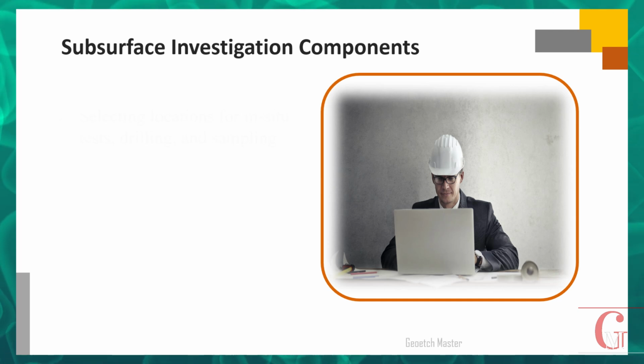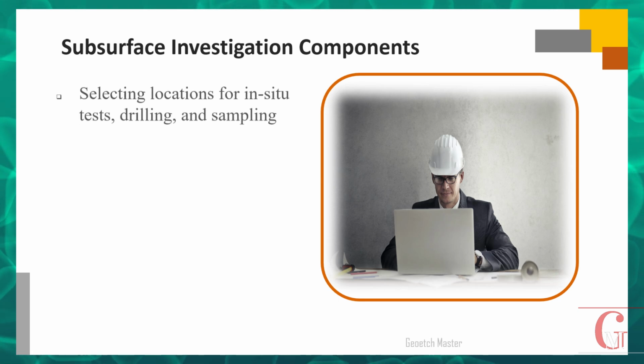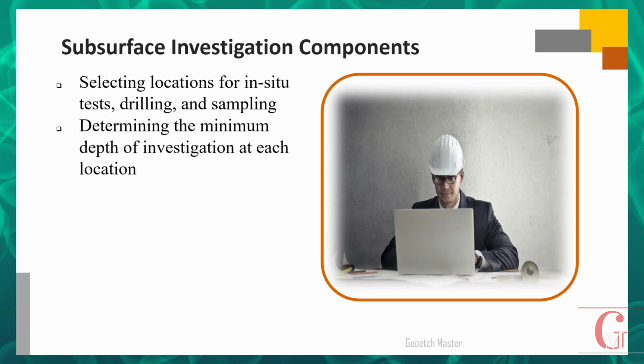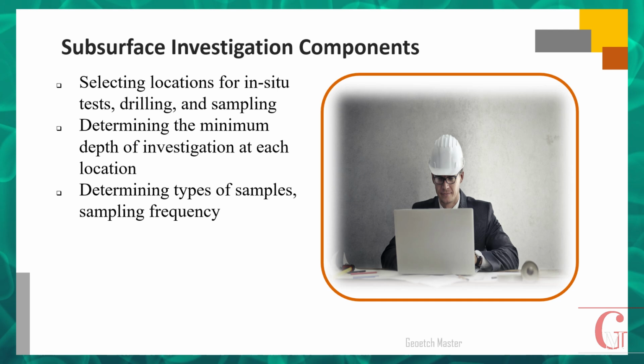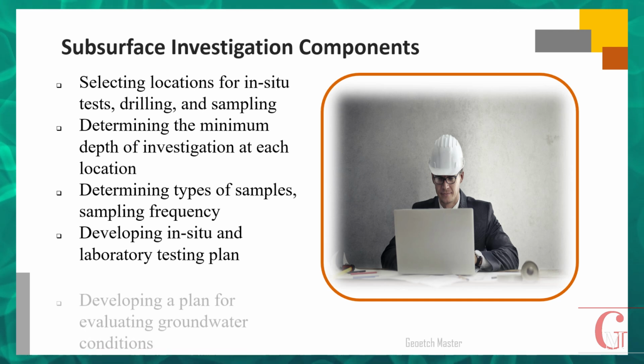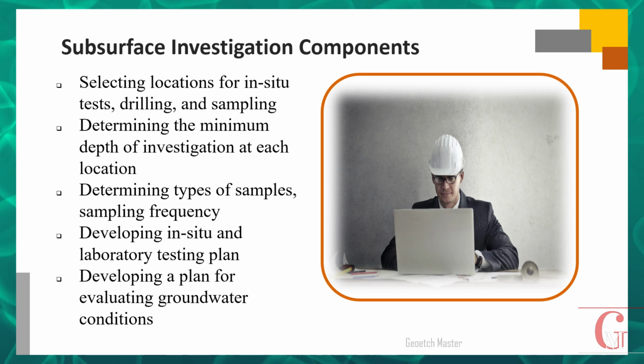So, remember, a geophysical testing plan is just one component of a larger subsurface investigation program. These investigations also include selecting the number and locations for in-situ tests, drilling and sampling, determining the minimum depth of investigation at each location, determining the required types of samples, and the sampling frequency, developing an in-situ and laboratory testing plan, and developing a plan for evaluating groundwater conditions.